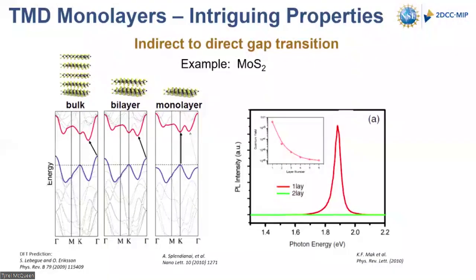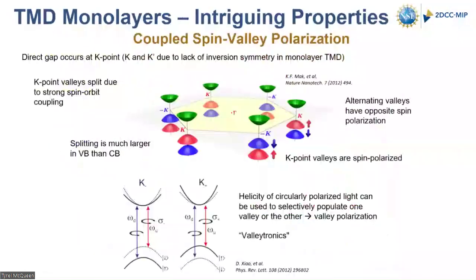The electrons and holes can recombine readily. And so, for example, if you do photoluminescence measurements on moly disulfide, the photoluminescence quantum efficiency is much greater from a monolayer of moly disulfide than it is from a bulk crystal, right? So really interesting, right? Now you can have efficient light emission just from a single layer of material that's only 3 angstroms thick, right? Okay, but even more interesting properties.